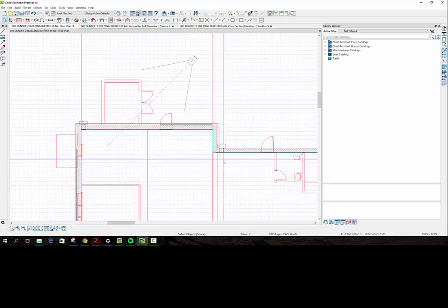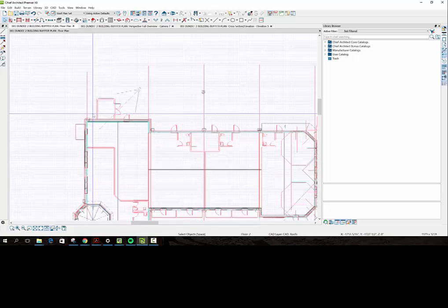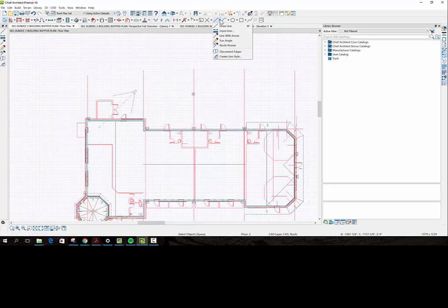All right, high point, nice and simple. And now we really need to, that's just going down to there, but we want to direct it to there, which it will get to if we're going to have a cricket. We're going to build a cricket up to direct it to there. Okay, so we're going to need a cricket there. So let's see how we're going to build that cricket.